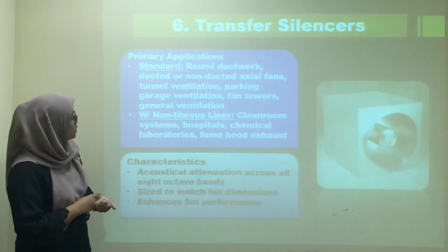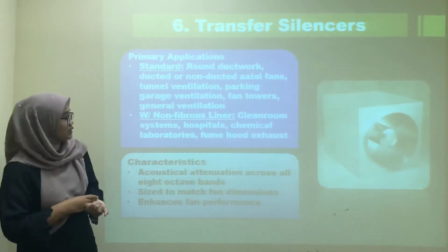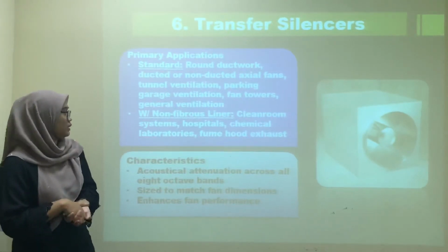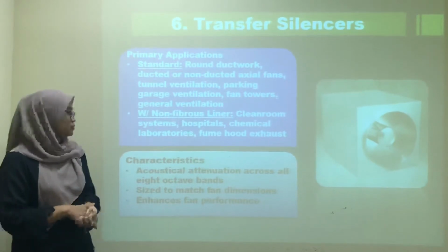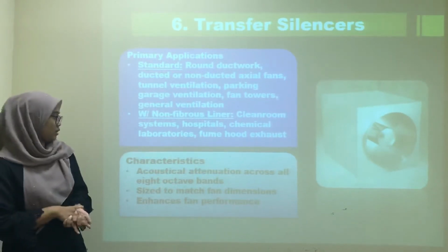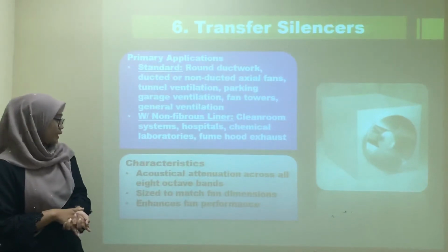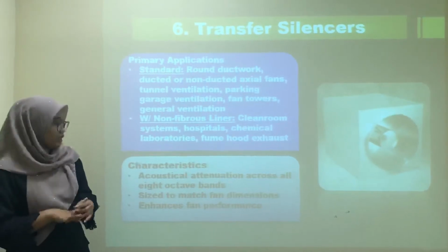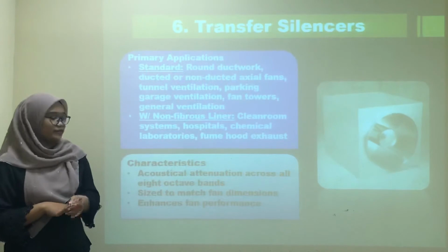For fibrous liner alternatives: clean room systems, hospitals, chemical laboratories, fume hoods. Characteristic: acoustical attenuation across all 8 octave bands, sized to match fan dimension, enhancing fan performance.